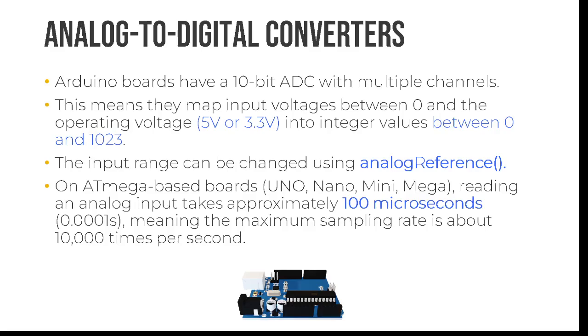In the Arduino, when you are reading the analog value, it takes just 100 microseconds, right? So it's not as fast as the flash ADC, but it's really, really fast, right? Because here we can read the 8 channels in the Atmega at that speed. It's not fast enough to make an oscilloscope with this, but there are microcontrollers you can use to build your own oscilloscope. This you can use to read signals that are not changing so fast. The rate is 10,000 times per second.